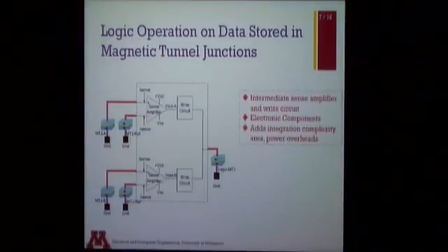So there are a lot of overheads. It is very complicated. And another subtle thing is that the resistance is not just read out and converted into current, it's converted into a bidirectional current. So a sense amplifier has to be designed in that particular manner.